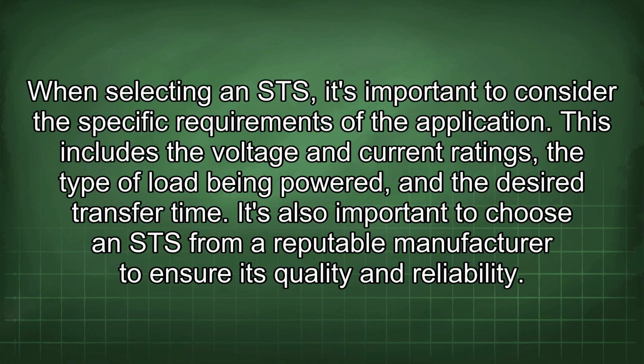When selecting an STS, it's important to consider the specific requirements of the application. This includes the voltage and current ratings, the type of load being powered, and the desired transfer time. It's also important to choose an STS from a reputable manufacturer to ensure its quality and reliability.